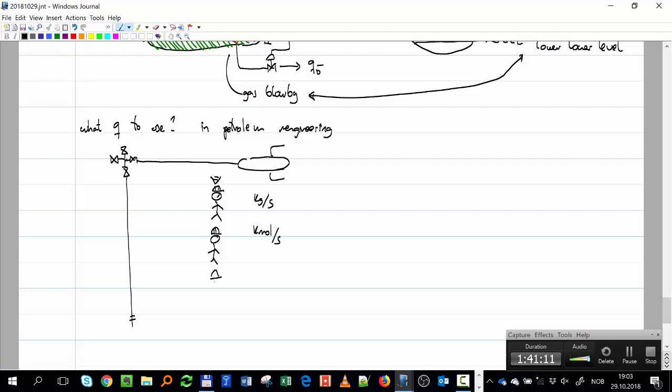Then comes the petroleum engineer, and he's saying so many in volume. A very strange unit, cubic meter per day. How come? Volume is not something that is maintained along the system. It is something that is changing; usually volume is a function of density. What is the relationship with mass flow? Q equals mass flow divided by the density, and the density is a function of pressure and temperature.